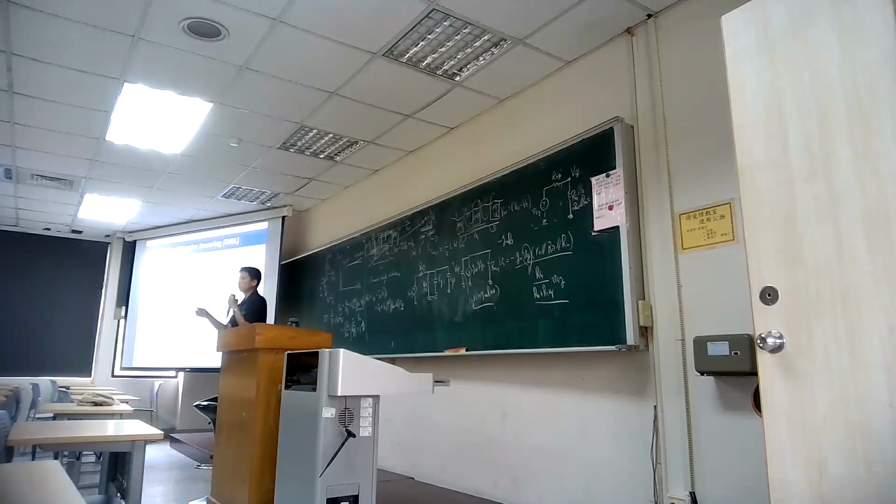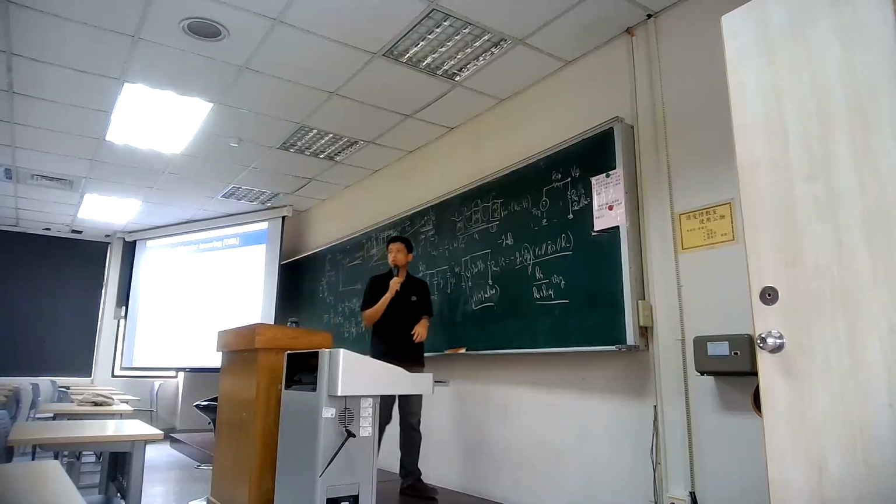To get the extra big current. And what is the extreme case? What is the best case? We get a gate all around. So your channel is like a round wire, and we get the metal around it. So you are able to precisely control how much current we can draw from the channel. So that's what people work on. I think about 10 nanometer technology, TSMC will work with that technology. And why people cannot work like this with FinFET, I will talk about in the next lecture.